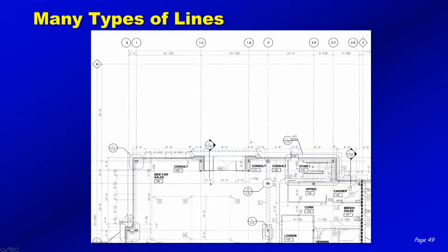And as you're looking at it, here's a floor plan, and you can see that this would be considered the object line. This little dash line here, what does that little dash line mean? Well, you're not identifying something that's hidden, because there's a leader coming up off of it with a section 1 on sheet 6.10. So that probably means that detail's been blown up someplace.